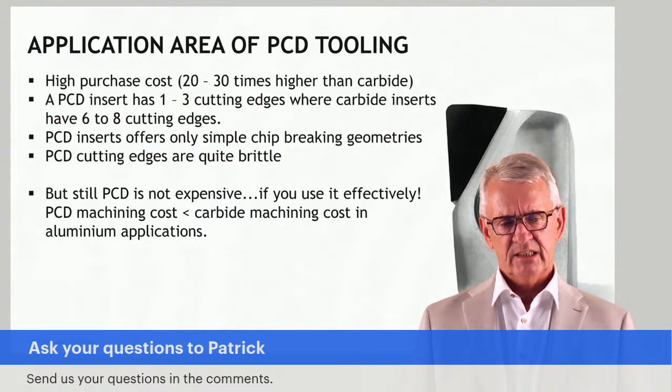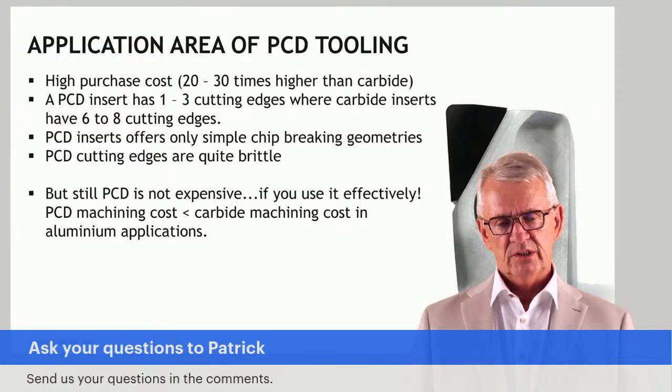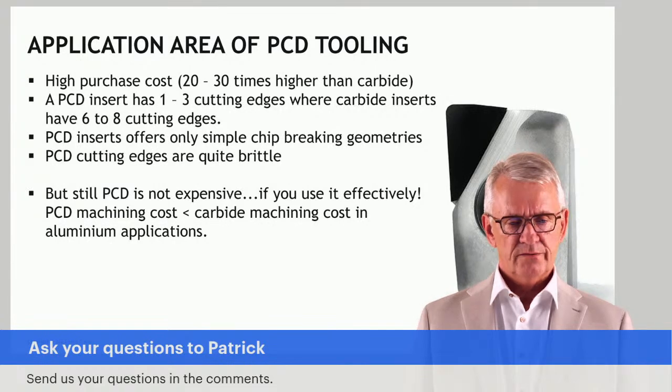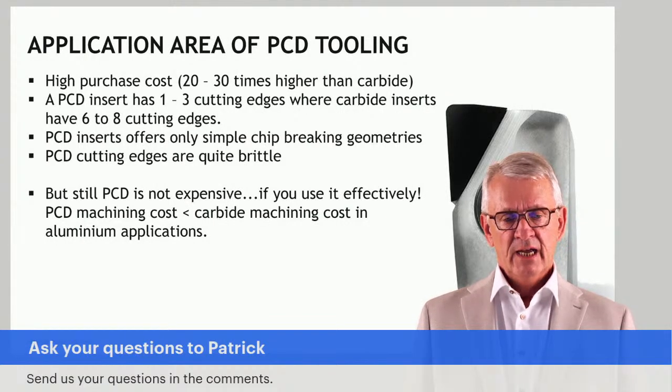If you consider using PCD materials, and that's why I said this should be a management selection first, because at first sight it's extremely expensive. Purchasing cost is high. Very often inserts have only one or a limited number of cutting edges per insert, compared to a lot of cutting edges on a comparable carbide insert.